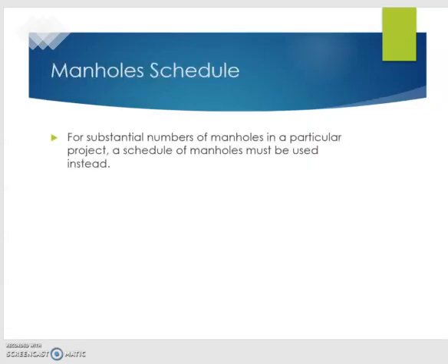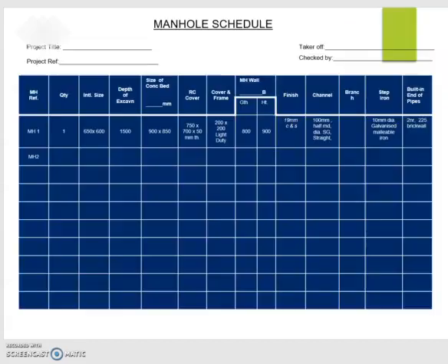Next one, we have manhole schedule. For manhole schedule, we are going to use this as well in the class. So just like you did your sump schedule, basically you have number of manholes that are involved, how many, quantity, what will be the size, depth of excavation, and so on.